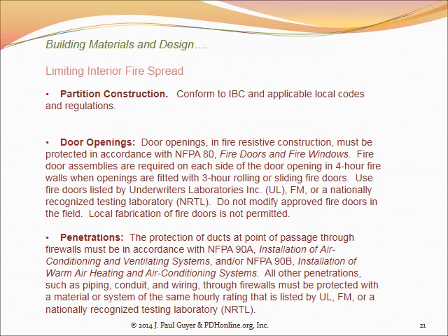So that in the event of a fire, one of the basic things that is done is to automatically turn off the air conditioning fan, so that the fan is not forcing the smoke around the building to other occupied areas.